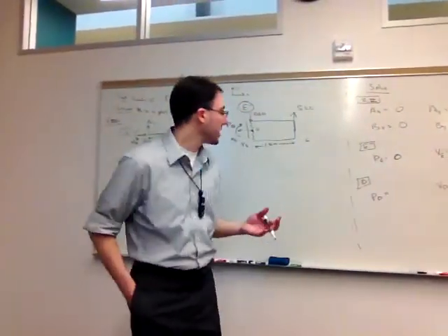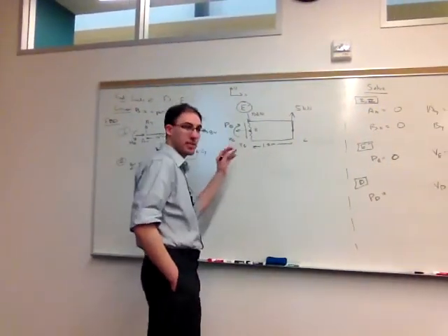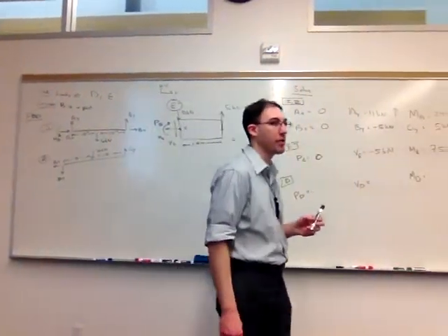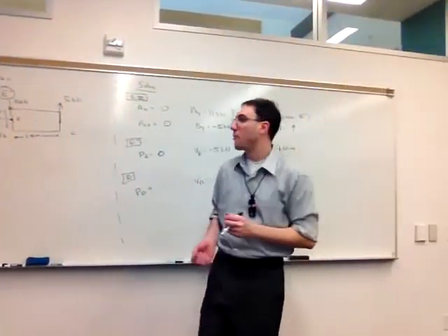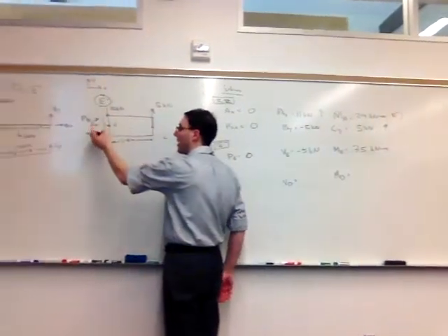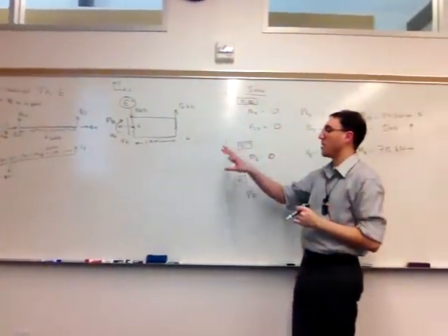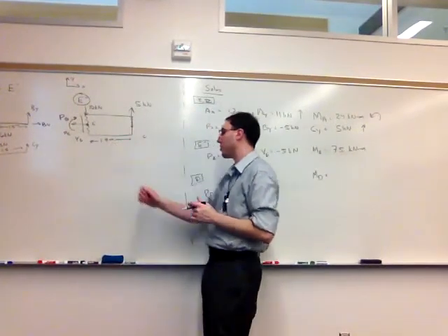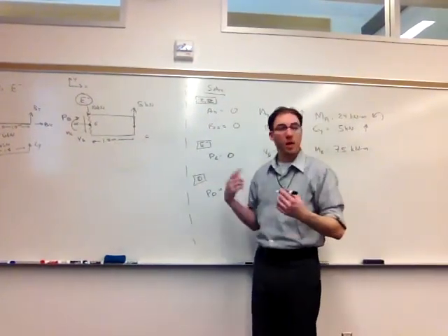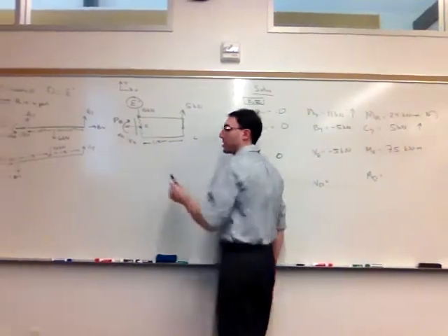Those are the three internal forces acting at E, or just to the left of E, so we're including that 10 kilonewton load in this picture. If we took the other side of the cut, that would not have it. But if you want extra practice to draw that side, you will get these same answers if you make equal and opposite direction assumptions also.